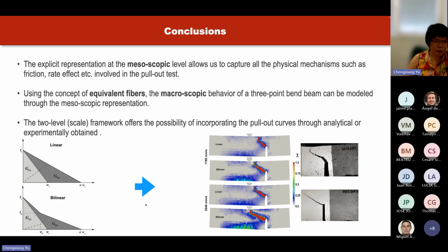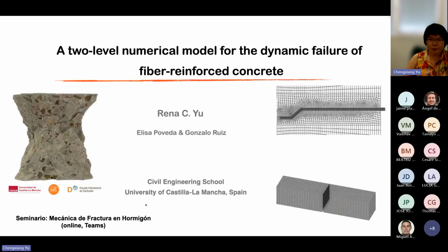Okay, so the curve below is from some simulations that we've done with mesh-free methods with Pedro Navas in Madrid now. In this case, we did not separate the fibers from the bulk material. So what we have is basically only changing the constitutive law of the uniform material, and then we have very good results. So next time we would like to get a more detailed level of mesoscopic simulations.